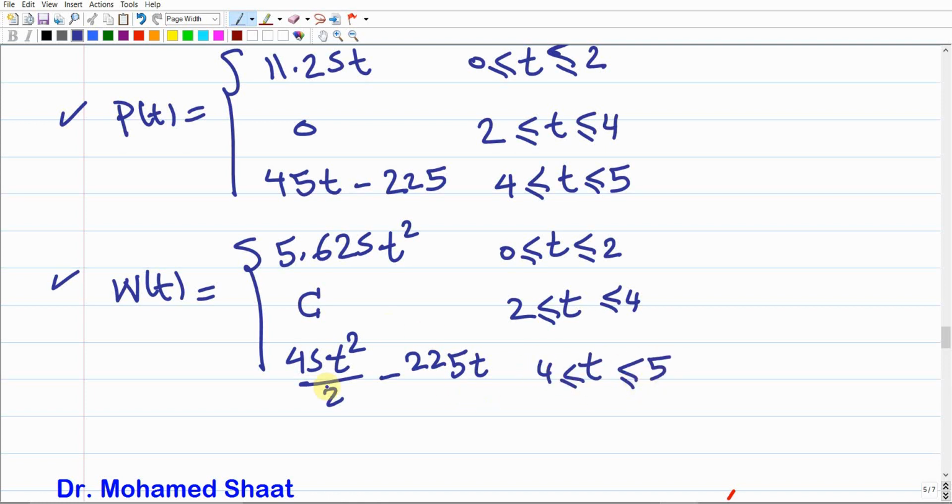You got my point? But this won't give a correct result at the end, unfortunately. Why? Because originally we are doing the integral of the power, all of this term in the power. Since we are not incorporating the integral limits, you should do the integral to the overall term as it is, like a single bracket, like a single parenthesis. The other option is just to consider that the power equals 1 over 2 L i squared, and this is what is recommended.